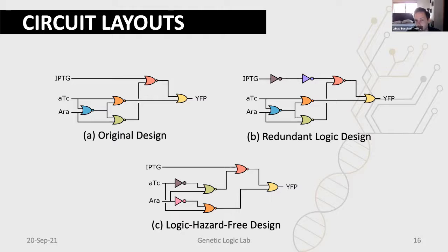I mean, 2 inverters do nothing. But they add extra delay, and the idea was that that helps with the glitching behavior that we saw earlier. We also have a logic hazard free design. For that, I want to kind of take a step back.